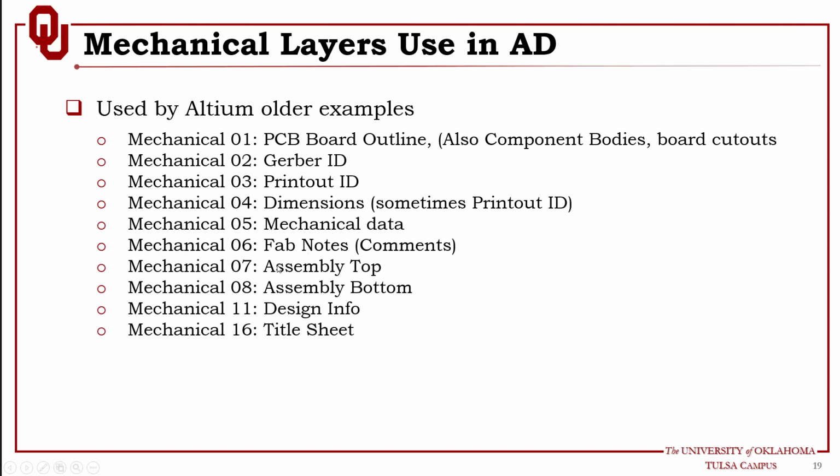Now these are component related and these are layout related mechanical layers. And if you look at Altium's older examples, you also have different configurations. You can take a look and keep this as a reference when you try to decide which mechanical layers you should use for your internal organization or your team.